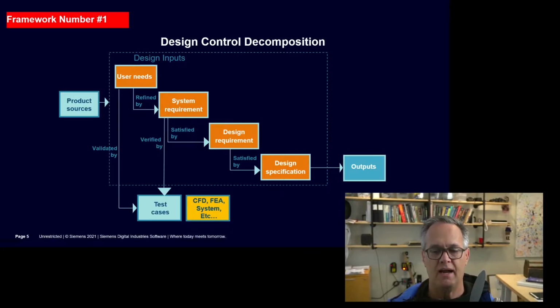We don't want to track everything related to risk, and the reason for this is there are things that are trivial. So we might have an outer skin where we're not particularly concerned about the location of any point on the skin, but the bosses where we're going to actually be attaching the skin to an internal part, those things we might want to be more concerned about.